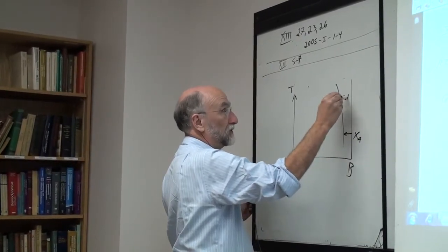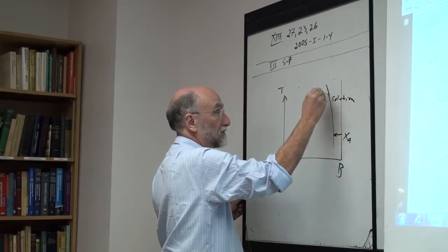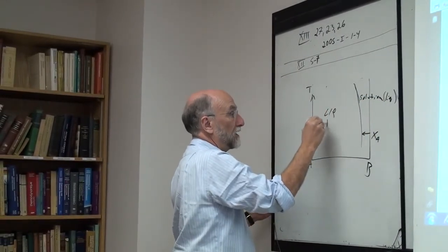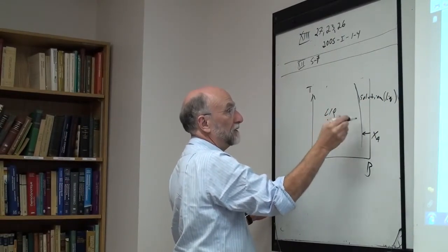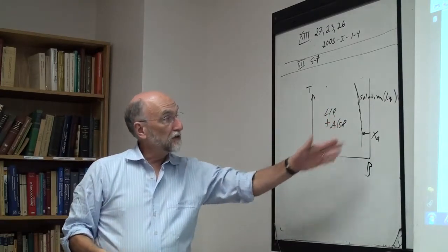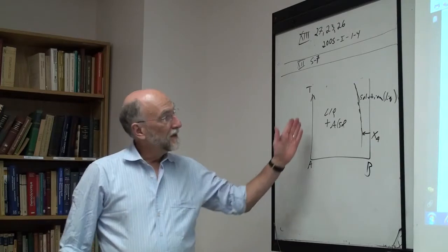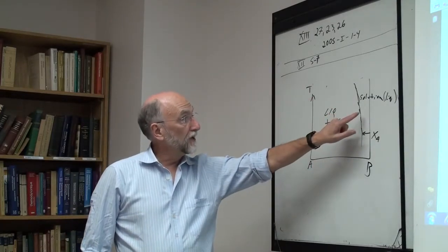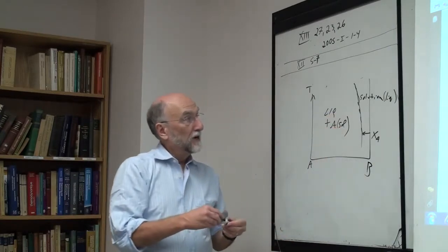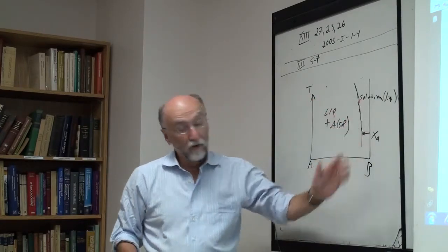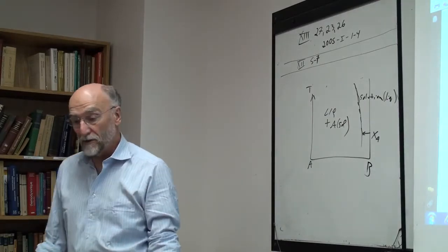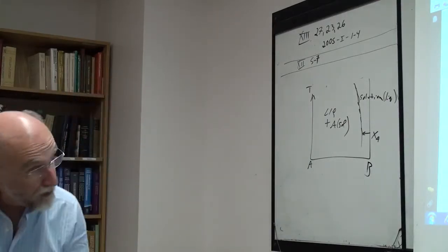Say it's a liquid solution, and here you have liquid plus pure solid A. So this is your liquidus line. The liquidus line and the solubility line are the same thing. That's the line of the liquid phase composition in equilibrium with solid A. But if this line is way over towards B, then basically it's a solubility line. It's the same thing.